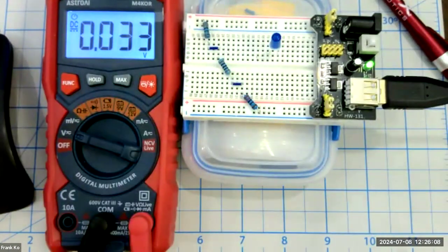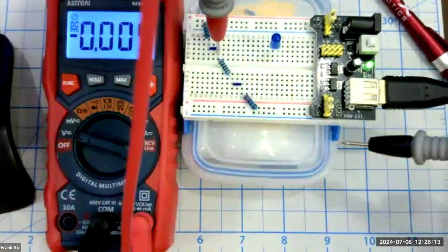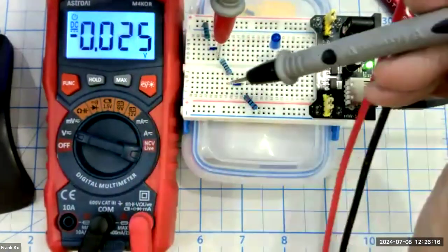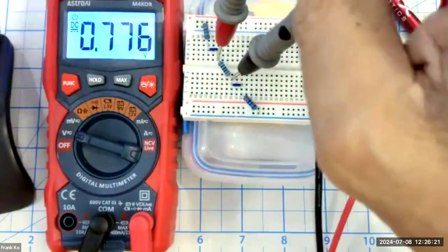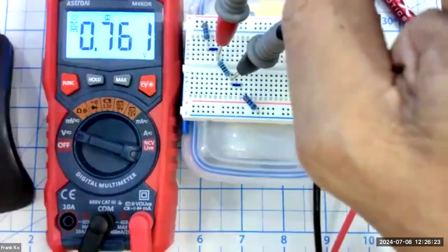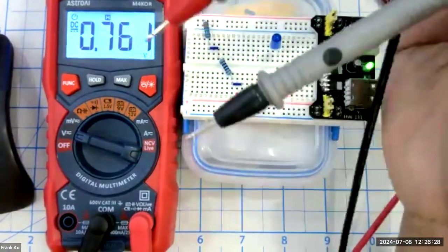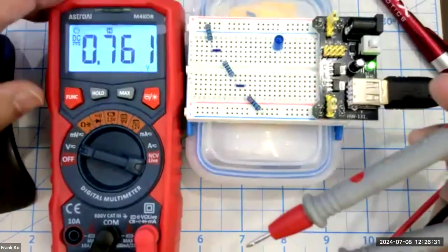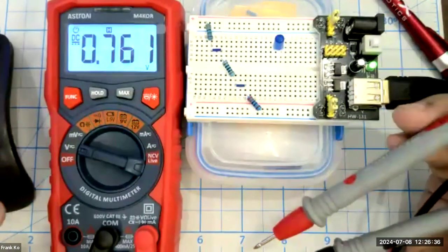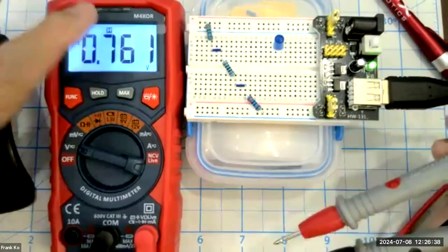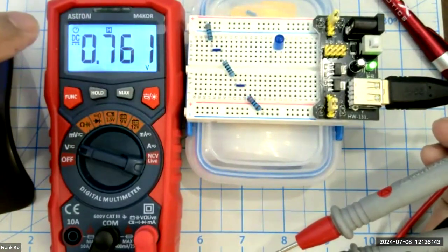Second one, we expected 769 millivolts. Let's see what happens here. Put this probe on here. Put this probe on here. Hold with one hand. Press hold. I expected something close to 769 millivolts. You can see I've removed the probes. I've used the hold button in order to hold the display because the display does jump around quite a bit. And so what you do is press the button to hold, jot this number down, and compare this to your calculated value of 769 millivolts.